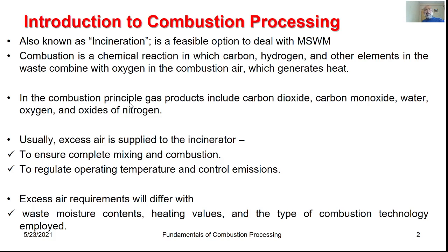In the combustion principle, gas products include carbon dioxide, carbon monoxide, water, oxygen, as well as oxides of nitrogen in addition to some other pollutants. Usually, for this combustion operation, more air than required, hence excess air, is supplied to the incinerator.